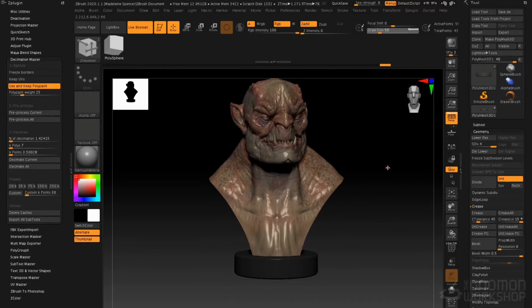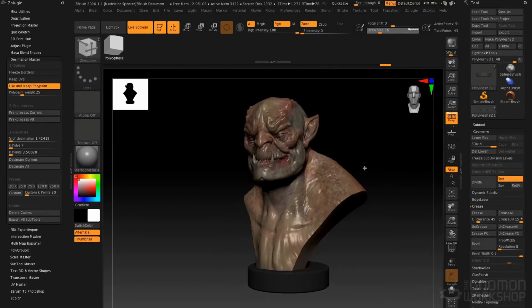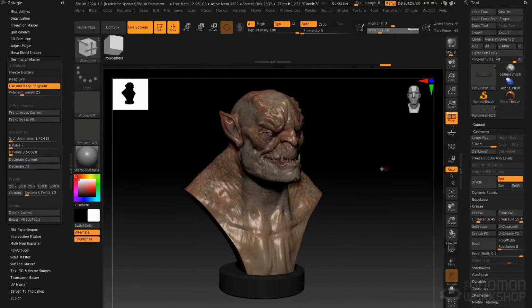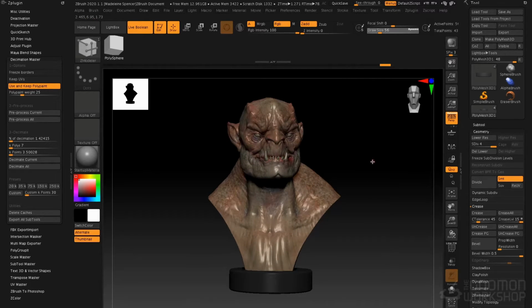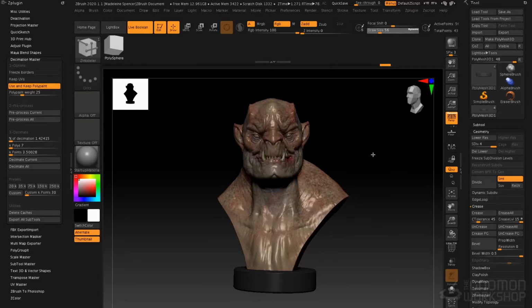Well, not quite. We need to set a scale, and we need to export it in a file format that can be opened by the print bureau, or you can upload to a website that does 3D printing like shapeways.com, for example. So what we want to do is export this as either an OBJ or an STL. Typically STL files seem to be the most common. It's sort of a standard file format for manufacturing, whereas OBJ is a standard file format in visual effects and games.